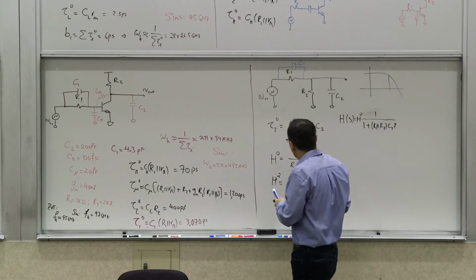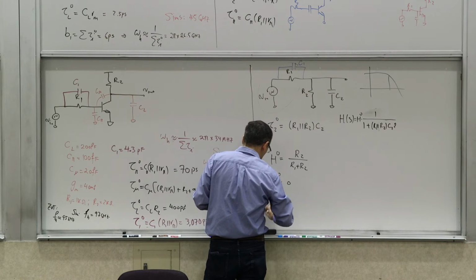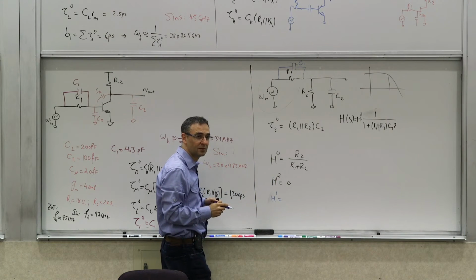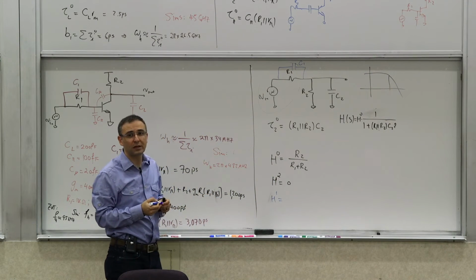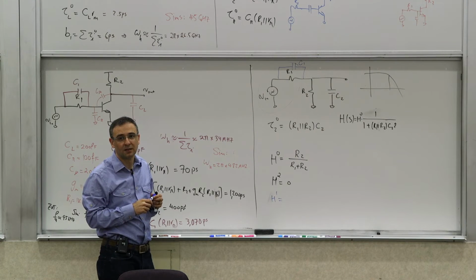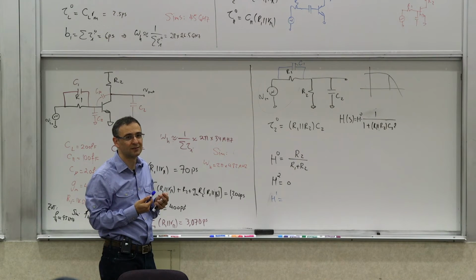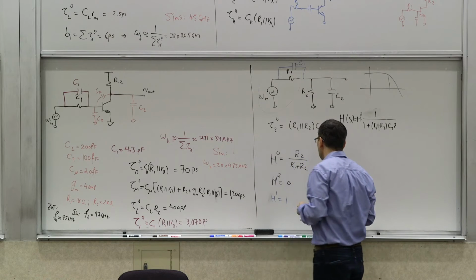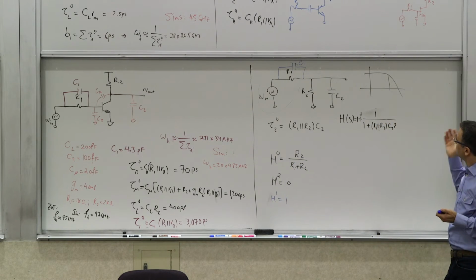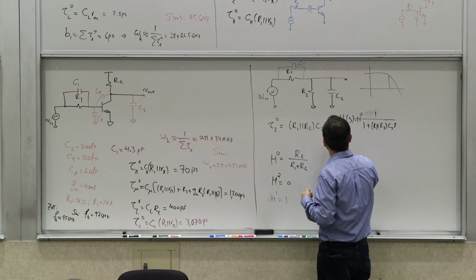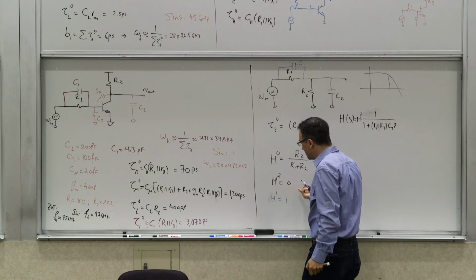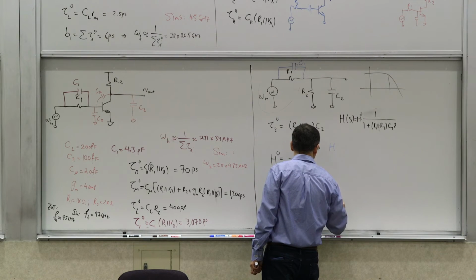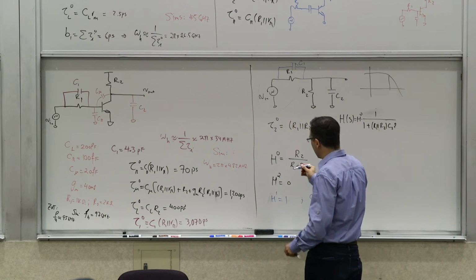To calculate that, the first thing you need to calculate is H1, right? So what is H1? When you take infinite value C1, what's the transfer function? It's 1, you're shorting the input to the output. So it's 1. And what is the new transfer function? H2 is still 0, so I know the only term in A1 that's non-zero is tau 1 H1 0, and we have to calculate tau 1 0.